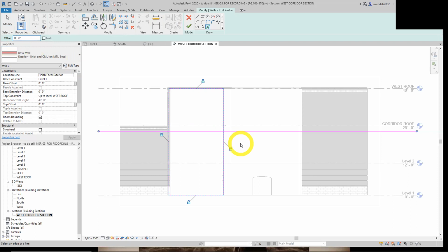And we're going to start drawing the lines. Select the inside walls, the edge. We're picking the lines we want to keep to form this shape. And let's start by, it wants us to pick the wall to the right first, which is kind of new to me, but I'm just going to go with it. It's established it. Now on page 135, it wants you to pick the exact lines to trim up this shape basically in sketch mode. So let's just follow along with their recommendation.